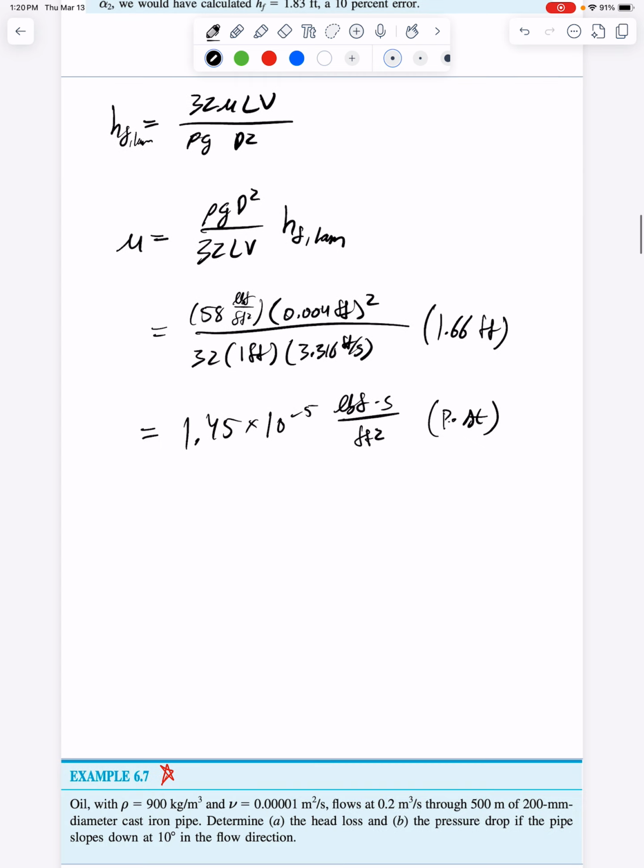And remember, initially we made the assumption that the flow is laminar, right? Now we have to double check the expression. Otherwise, we basically solved a different problem, and you're gonna lose a lot of points from that. So let's check Reynolds number.